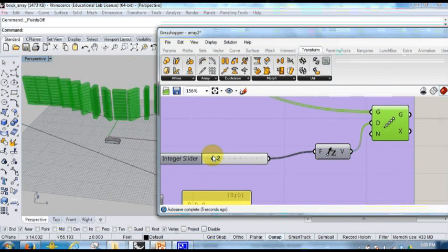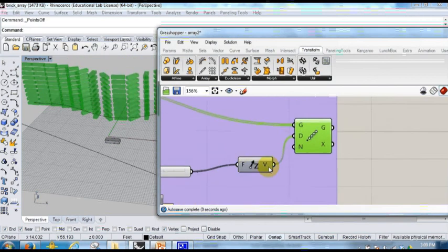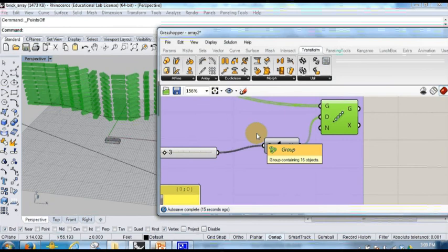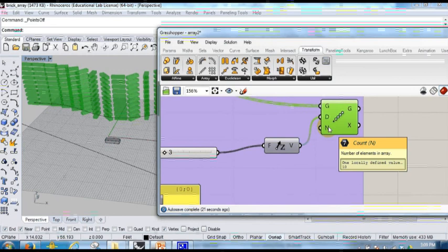So you can have higher, lower brick walls. Is that just a vector? It is a vector, right? The vector means a direction, like an axis. To tell you it's the z-axis. And the n value is the count. So right now it's 10 by default. It will duplicate 10 layers.